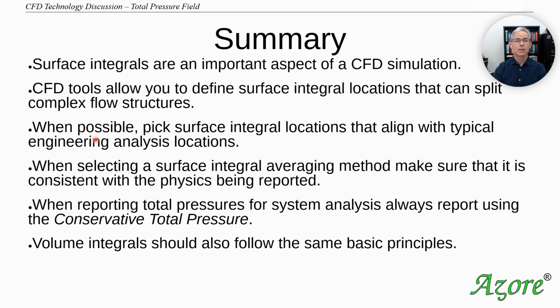When possible, we want to pick surface integral locations that align with typical engineering analysis. So we would probably not pick that plane 1 in the example we just did, because it would be hard to even measure. You would probably pick planes within the piping structure at different locations where you might have a pressure tap, where you could get engineering information.